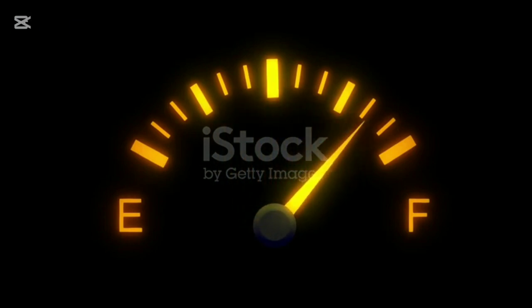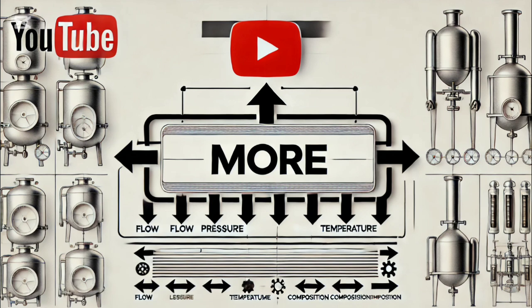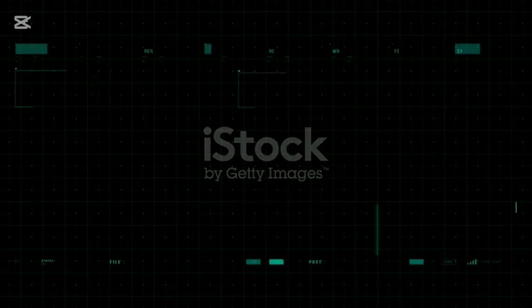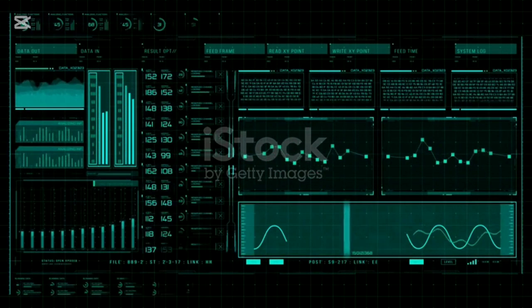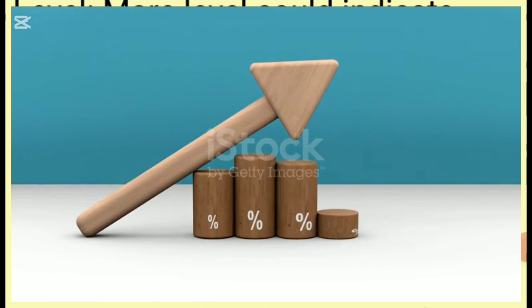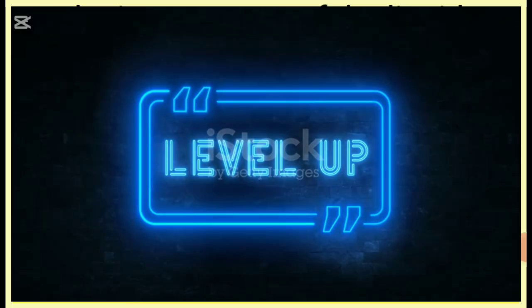Temperature: more temperature might occur due to overheating or excessive heat input. Deviation: more temperature in a stripper boiler could lead to thermal decomposition or overheating risks. Level: more level could indicate overfilling of a tank or vessel, resulting in carryover of the liquid.